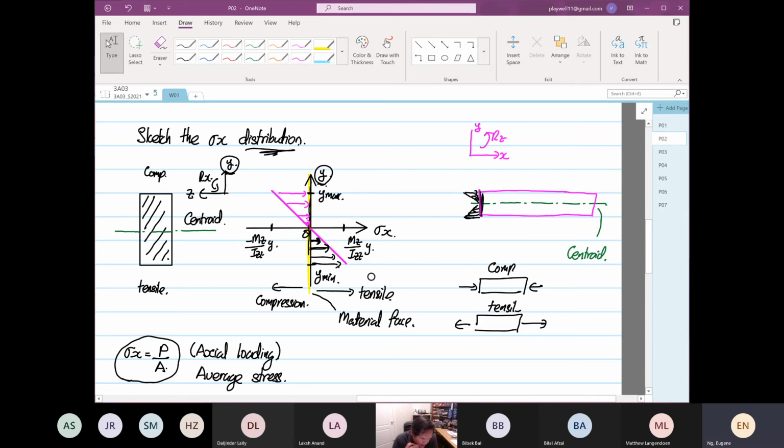So the next thing I want to highlight, I think is important to know, before we do bending moment calculation, we have to know why we are analyzing structures at a certain point. Like what I told you earlier, we usually analyze structure where it's going to break. You don't calculate stresses where the structure is least likely to break.